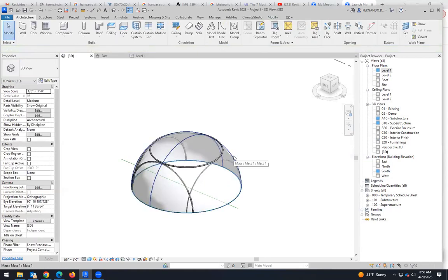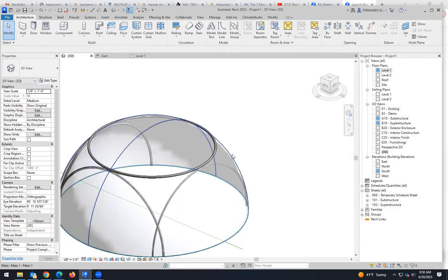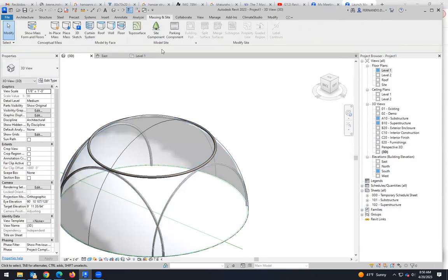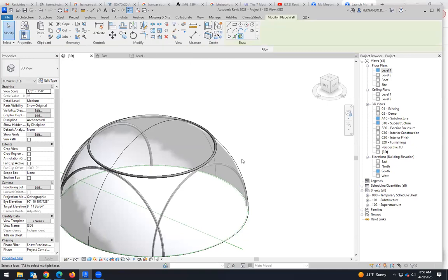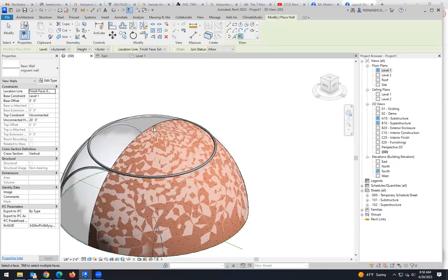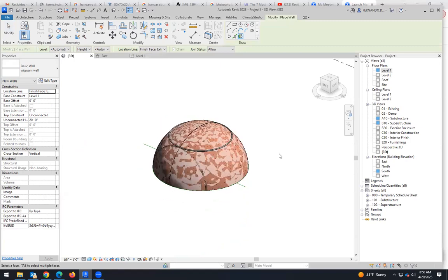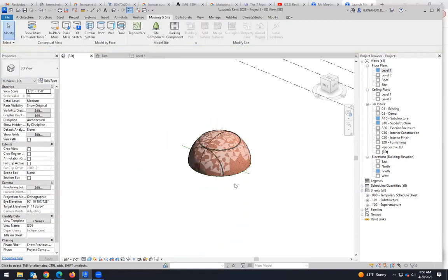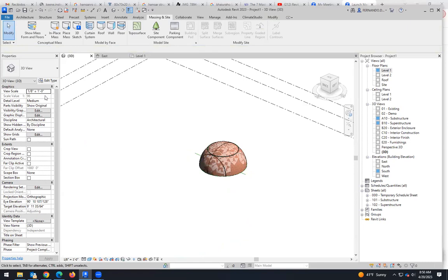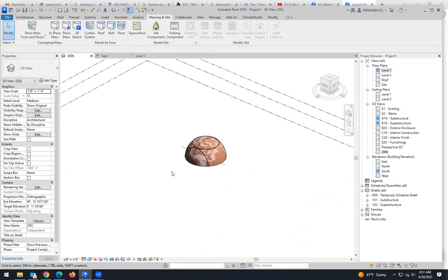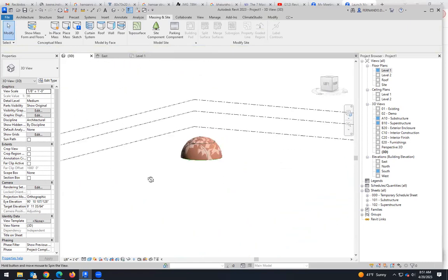And then if I design this basic Wigwam wall, now I can assign this shape with a material, but I don't know if it's a wall or a roof. Let's find out. So if I go to massing and site and I select wall by face, can I select this? Yes, I can. Okay, so I can select this, and it has an actual material there. So with that material, I can test some thermal properties.